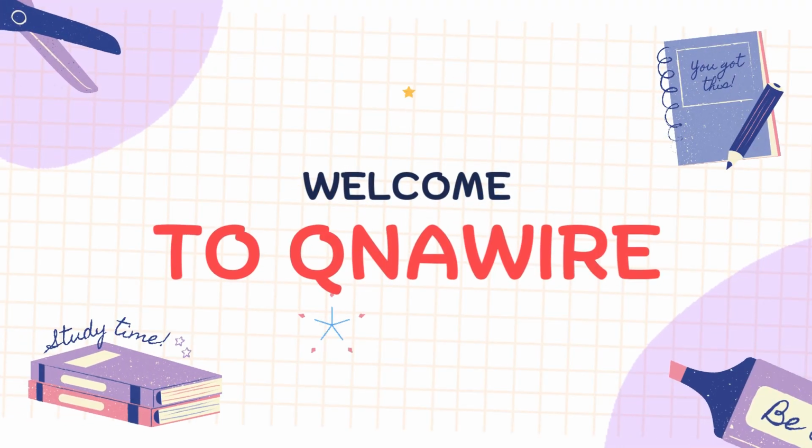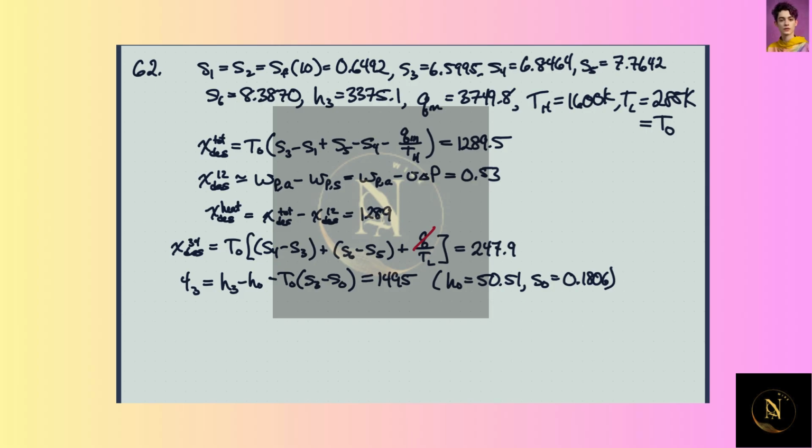Welcome to qnawire. In this problem, we're going to go back and look at problem 37 and look at the exergy destruction. Again, we can get the entropy at the pump, because we're going to assume it's a saturated liquid at 10 kilopascal. So we get the entropy at the inlet and the exit of the pump.